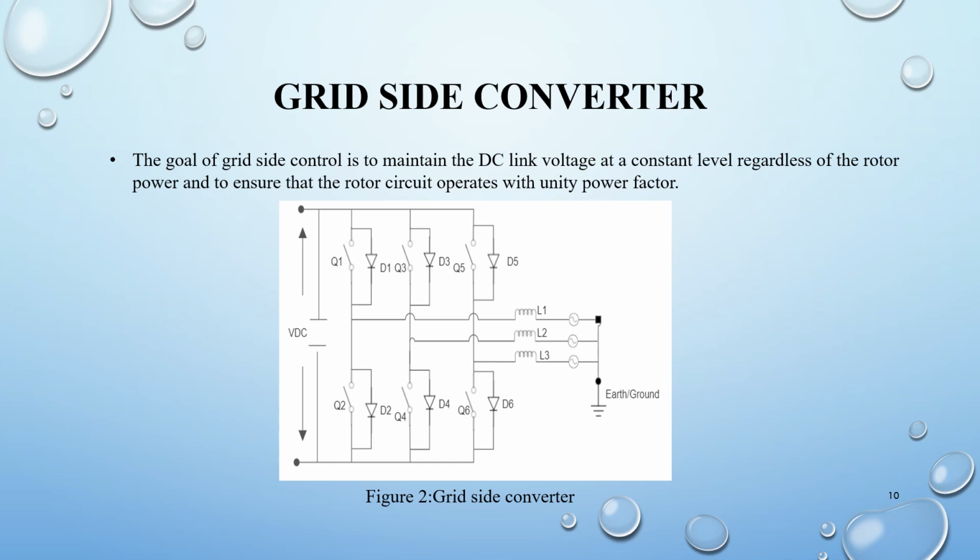It has the ability to switch between DC and AC voltage and current, as well as between DC and AC power or AC and DC voltage. An ideal switch is frequently built with antiparallel diodes and a controlled semiconductor to enable current to flow in both directions. An insulated gate bipolar transistor, or controlled semiconductor, is used in this discussion.